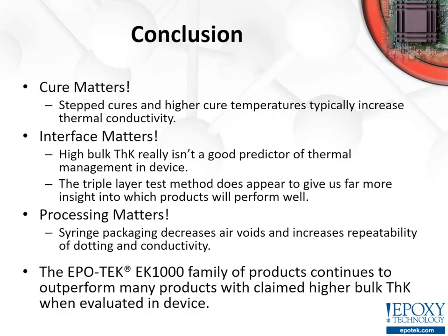On to the conclusions. First, cure matters. Stepped cures and high cure temperatures typically increase thermal conductivity. An optimal cure will help optimize your thermal conductivity. Interface matters. A high bulk thermal conductivity is not a great predictor of the actual thermal resistance in device.